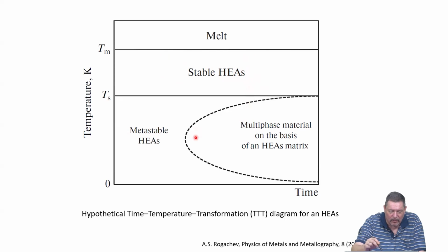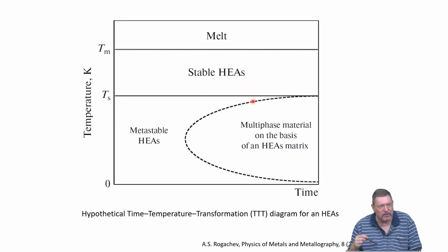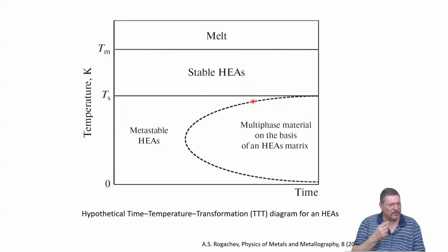But if you go lower in temperature, obviously the T times S term gets less dominant, enthalpy becomes more dominant, and it means very often you go through a region where you have solid solution only as a metastable phase, which is in competition with another phase that forms and destabilizes your high entropy system.